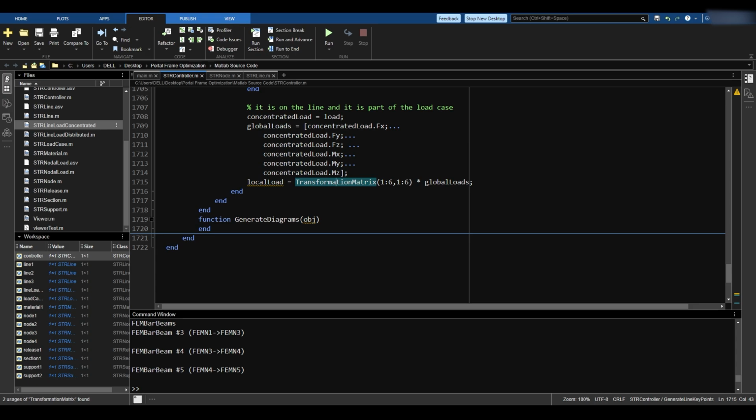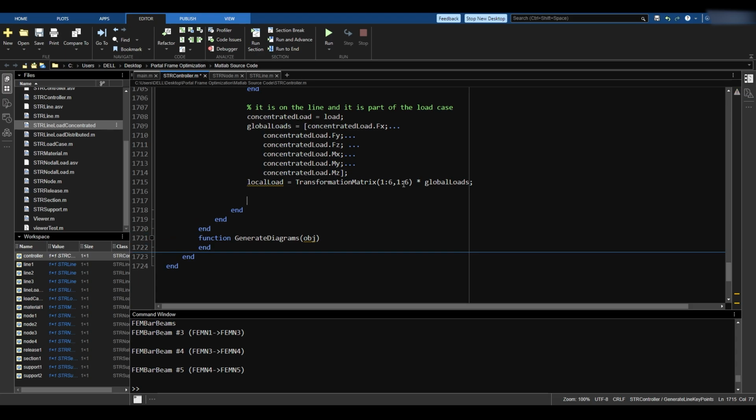It's time to define the line key points. There are 2 options for the line key point definition here. Now I could just go in and say LKP equals and define a line key point, but there is a problem. The line key point might have been defined before. And if it was defined, I must modify and add to it. If it was not defined, then I do not need to add to it.